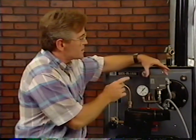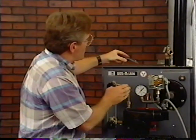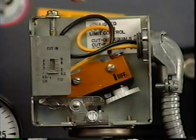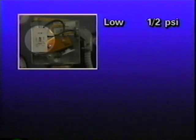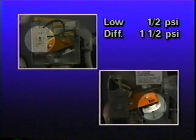Controlling the cycling of the steam boiler is the job of the specially designed steam pressure control, often referred to as a pressure troll. Many steam pressure controls have two settings: low, or burner on, and a differential setting. On this pressure control, the low setting might be set at 1/2 psi, pounds per square inch, and the differential set at 1.5 psi.